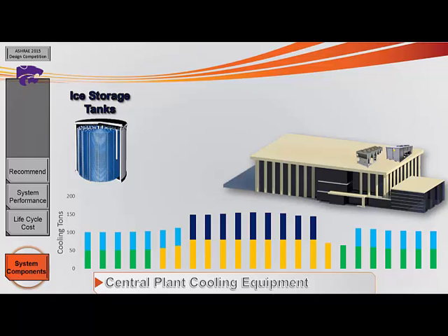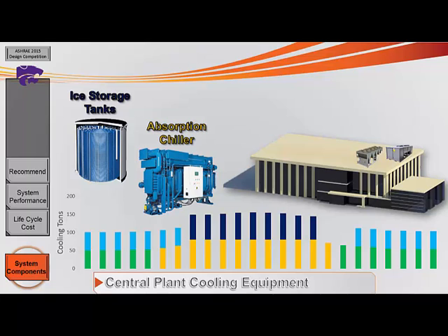The ice storage will assist the absorption chiller in meeting the daytime cooling load. The ice that is created is stored in large tanks below the building. When the cooling need exceeds the capacity of the absorption chiller, water flows through these storage tanks, cooling the water.